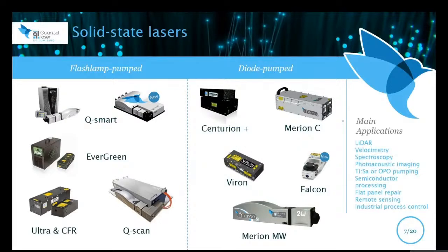Let's start with the solid-state laser offer by Lumibird. These are mainly based on neodymium sources. Both pumping technologies are offered: flash lamp pumping, which is affordable but short-lived, and diode laser pumping, more reliable. This page gives an overview of the various products designed for specific usage: scientific, defense, spatial, medical. The lineup covers a very wide range of optical energy, going from 10 millijoules up to nearly 2 joules, depending on the model provided.